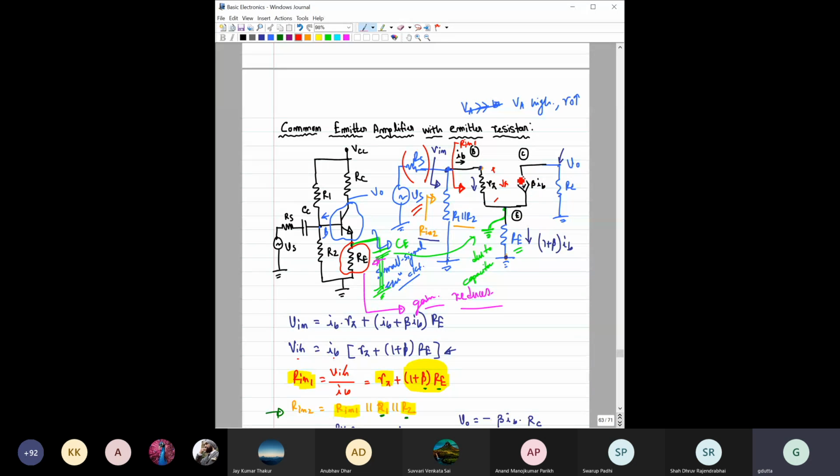So please figure out what will happen if you have one more resistance across this, here RE2. How much of Vs will fall across this R pi? And from there, you will find the value of the small IC. From this, you should also be able to find this output voltage. So from that, you will be able to see whether the gain is really increasing or really decreasing.